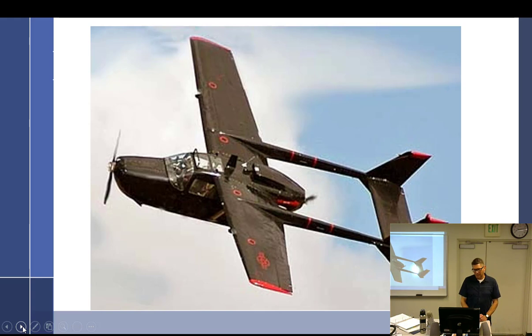My understanding, not having piloted one, I've flown in them, is that if you lose an engine, you're struggling. I guess they do okay, but with Cessna gear, the way it comes up, it turns and creates massive amounts of drag before it goes into the wheel well. So if you lose an engine and you're sinking and you decide to lift the gear up, you're going to sink even faster.